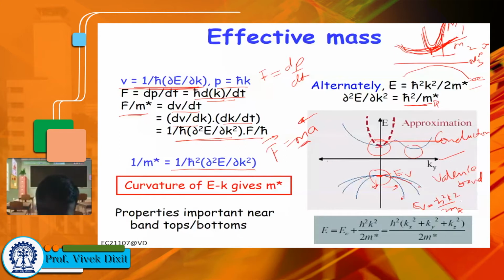So that means this kind of E-k diagram, where there's a flat line, will correspond to a band where particles don't move. That means particles are confined. This is basically like an impurity level. So in that band they cannot move. Once they acquire energy and change the band, then they can move, but in that particular band they cannot move. So they are basically localized carriers.